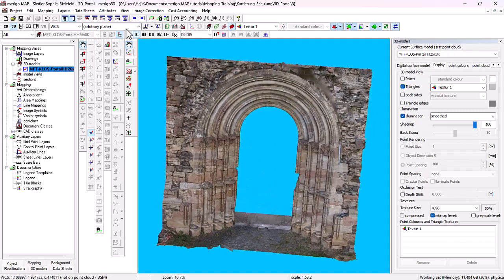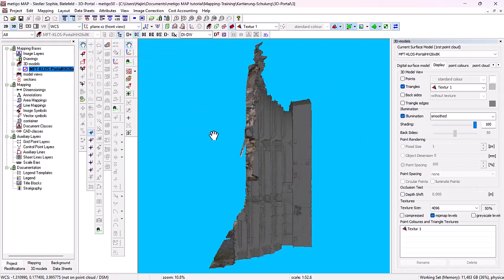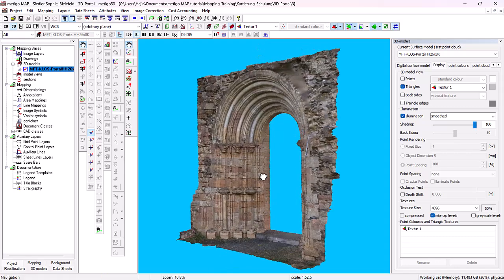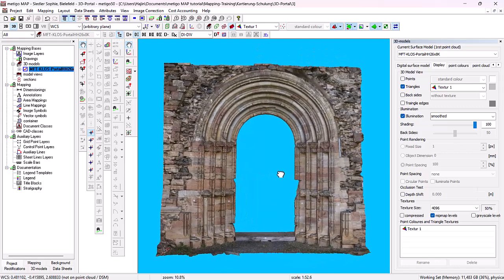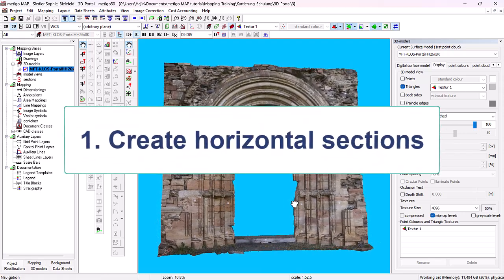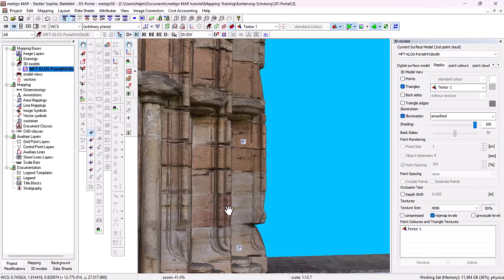The current world coordinate system comes from the overall structure of the church and is therefore not usable for this. So now we want to create new user coordinate systems with the possibility of the two-point plane. Two-point plane means I define the x-axis of the coordinate system with 2 points, and the orientation of the height remains vertical as in the subordinate coordinate system, and also the height reference is passed automatically. And I need a horizontal section for this.